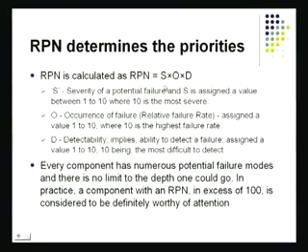So I've got here the same formula. S is the severity, O is the occurrence of failure, which is the probability, and D is the detection capability. These things together, when they are multiplied, you end up with RPN. RPN is the risk priority number, and if you have RPNs on different actions, you should really go with the one that has the highest RPN. First attempt that one, then go to the next one, then the next one, and so on.